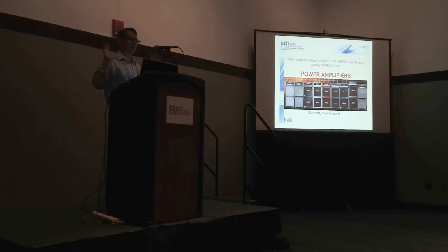Gallium nitride is really the Marshall stack of the amplifier world. And with good reason. You can make some great power amplifiers on GaN, very efficient, very high power, very small. And that's really been the dominant research focus for gallium nitride. But I'm not an amplifier designer, and so one of the things we asked at Custom MMIC is, what else can we do with gallium nitride besides power amplifiers? Because there is more.